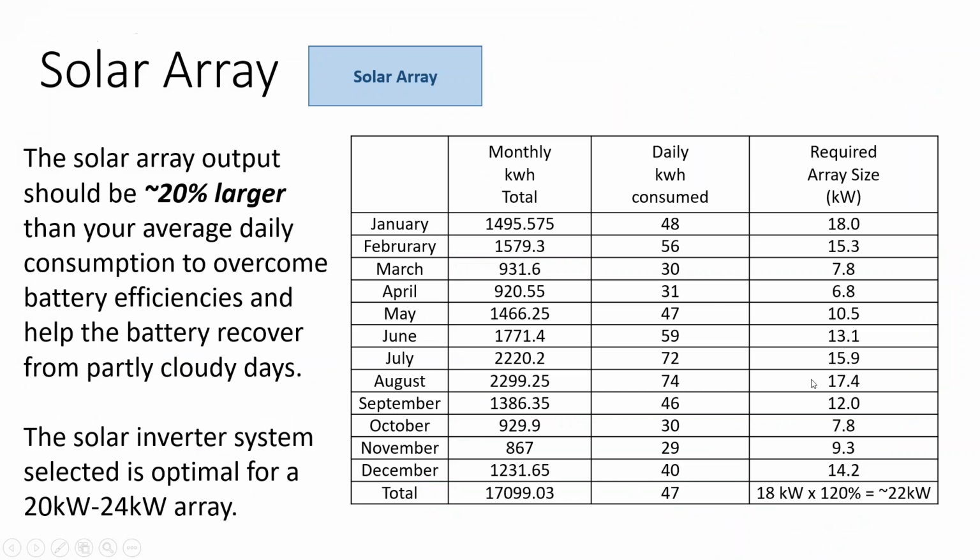And so all we had from the client going into this off-grid design was their monthly electric bill. So he said that in the month of January, he used 1,500 kilowatt hours. And then in the months of June, July and August, he used over 2,000 kilowatt hours. But we didn't have any interval data.